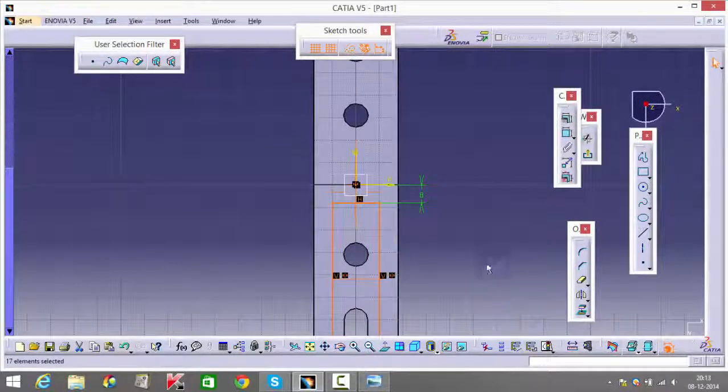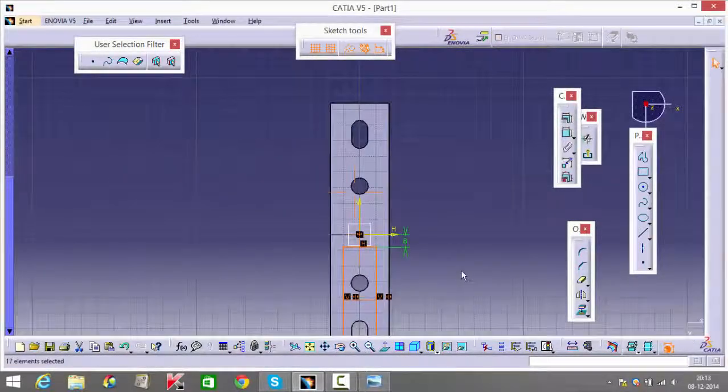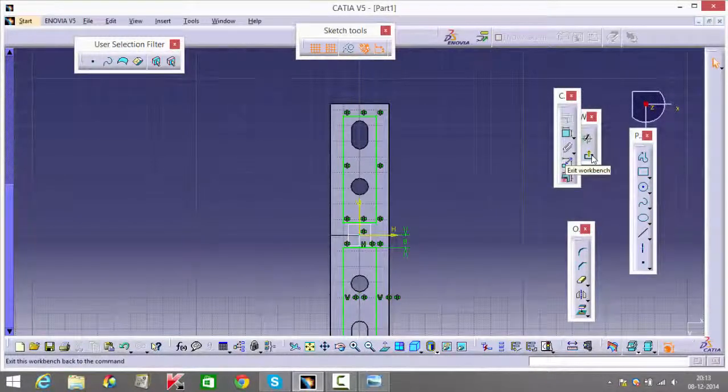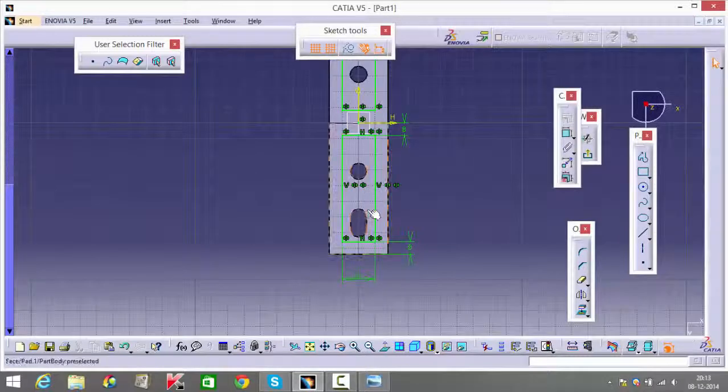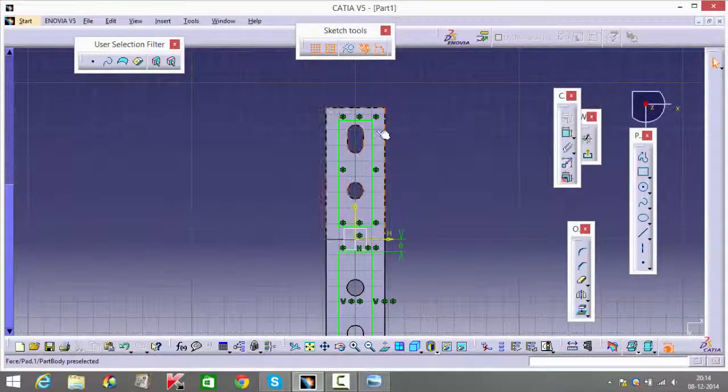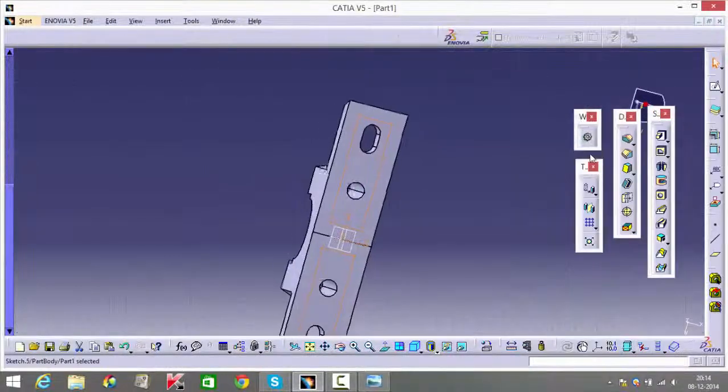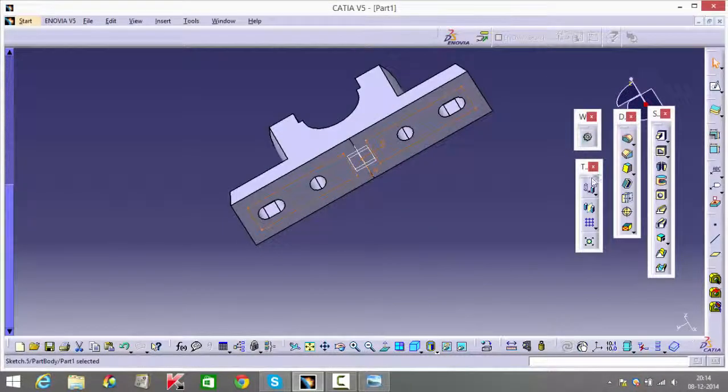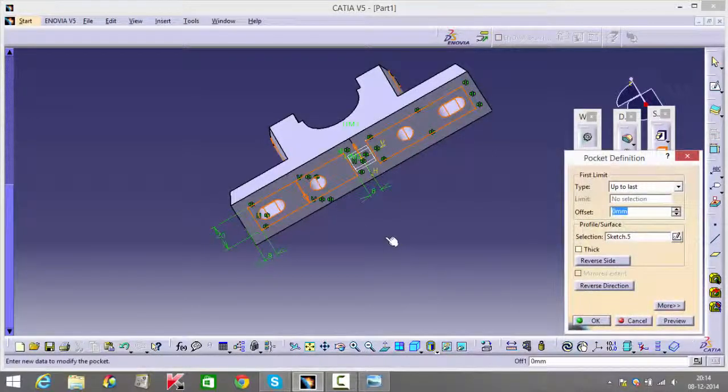See, this is the best part about CATIA. You have several options and you need to venture out and see how these options work. You don't need to individually make all these different parts. You don't need to make one box here, make the constraints, another rectangle here, make the constraints. All you can do is just make one and mirror it if you require it. If you don't, then in some cases you'll really need to do it individually. So just check in what scenario you'll need to use that.